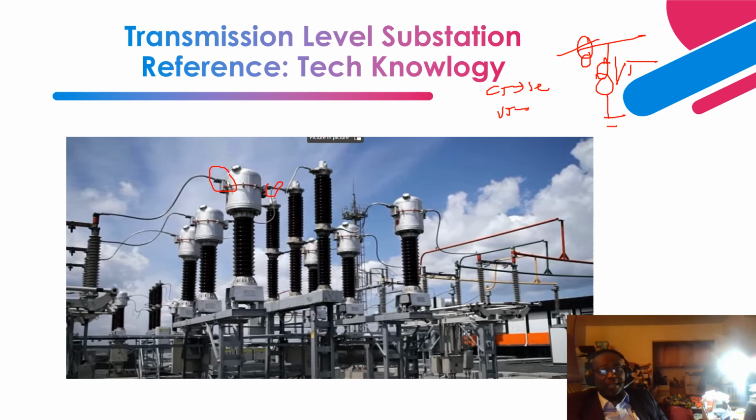As you can see over here, this is a CT. This is a high voltage inductive type of CT, which has windings that are immersed in oil. It is able to step down the current, from, let's say, a rated current of 4,000 amps, to 5 amps or 1 amp for the metering circuit or your protective relays.